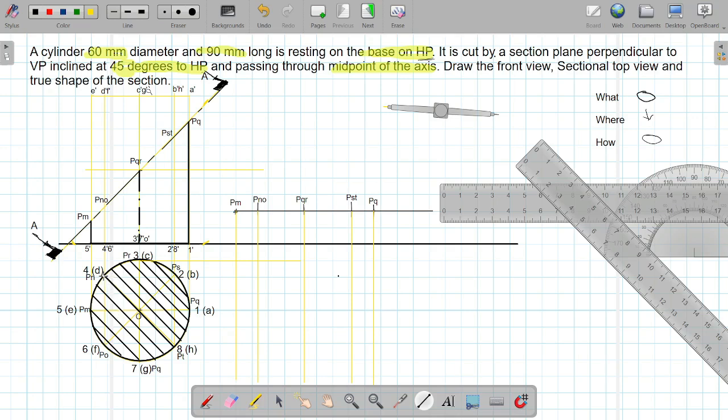So starting from this, it will be projection from this side. Then projection from this, projection from this point, and finally projection from the last point. Now wherever they intersect, that will be named as that point. For example, PM from top and PM from the left are intersecting at this particular point, so this point will be named as PM.